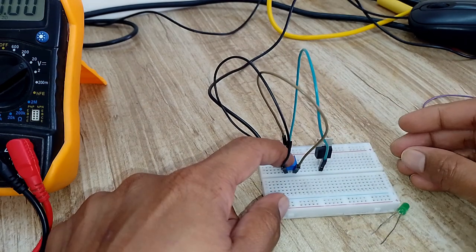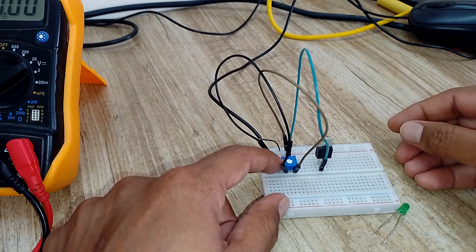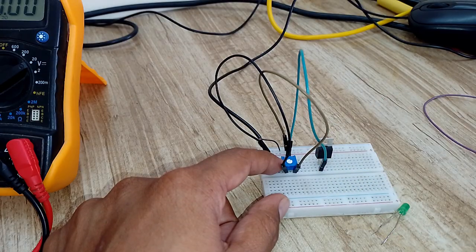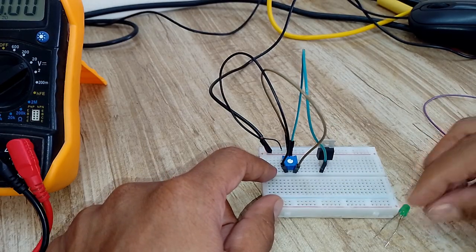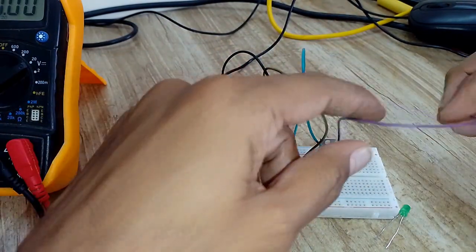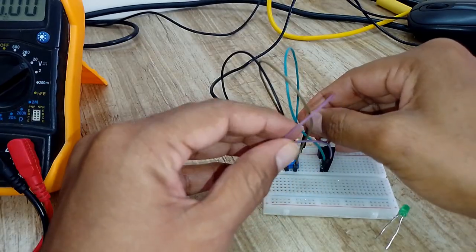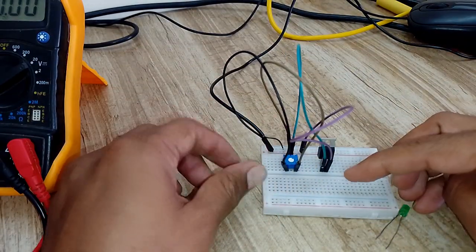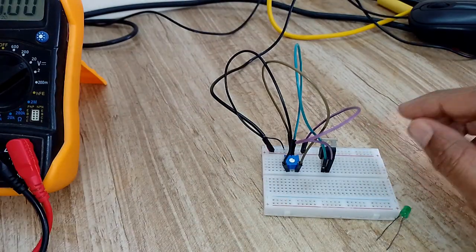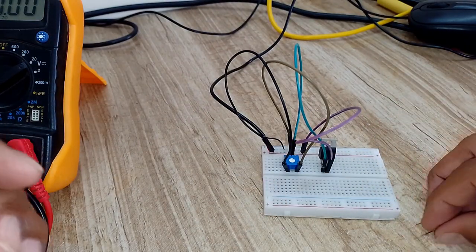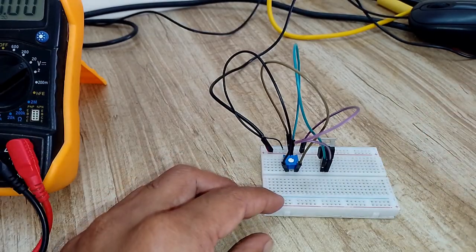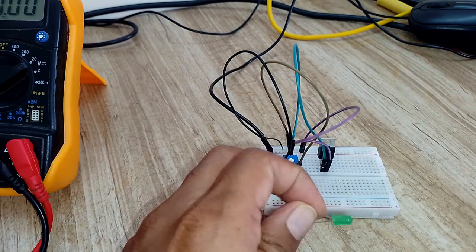See, now whenever this potentiometer, that is this trim pot, is varied, the voltage at the gate will vary. And for the drain you have to give the supply. So I am directly giving the drain supply from our positive, which means I am directly giving the 8 volt to our drain. You can give any voltage to a drain. This MOSFET particularly can handle nearly 100 volt. So you can give any voltage depending upon the load. Before using any component you have to make sure that you read the data sheet.